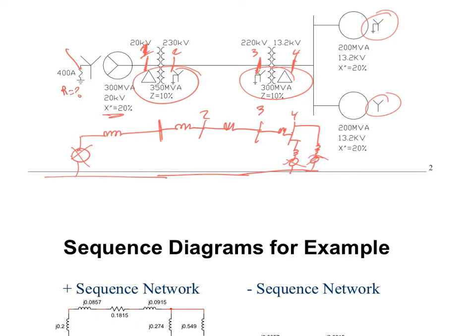So what is the actual voltage? Isn't it 20 kV divided by 400 amps? But be careful. What type of voltage is this? A three-phase line voltage. I actually want that to be a phase voltage. So to solve for the R value, you solve for the phase voltage, 20 divided by square root of 3, divided by the current, and that gives you the amps.